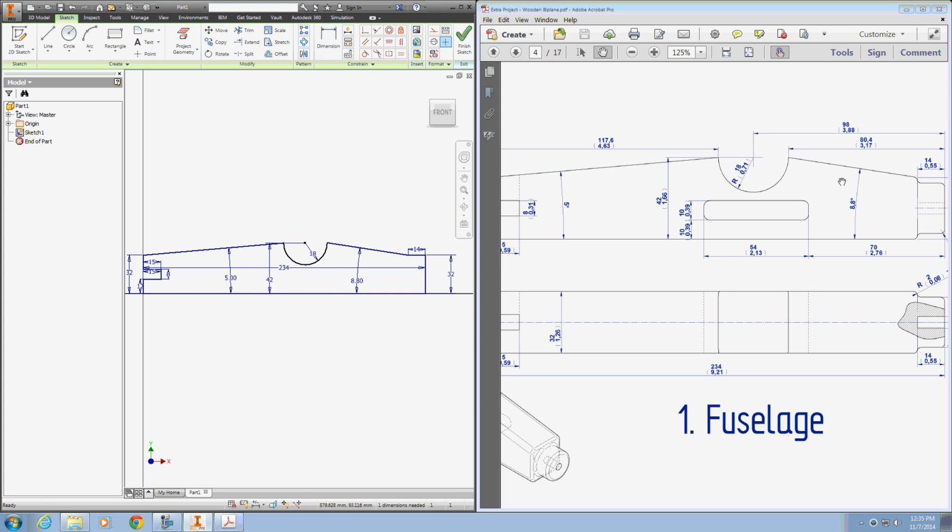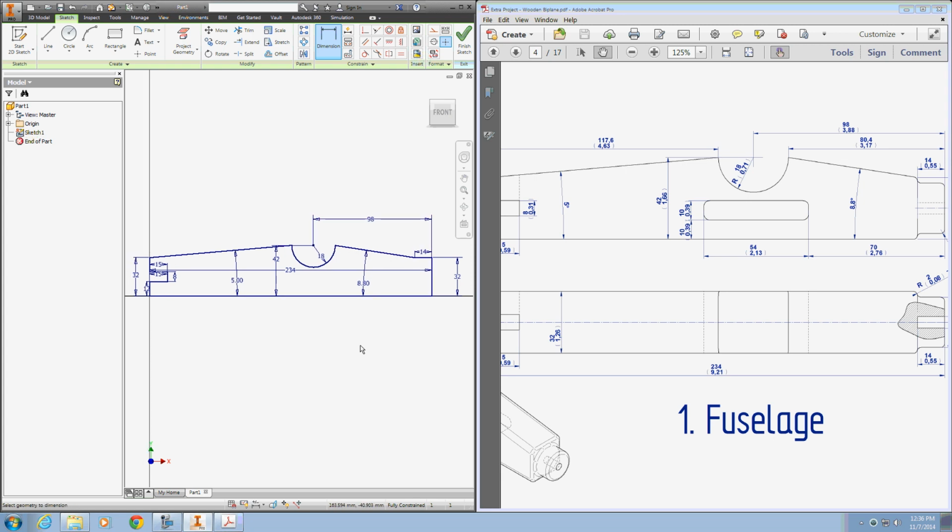And then it is 98 millimeters from the front to the center of the arc. And with those dimensions, it is fully constrained. I do not need to use the 117.6 because the angle and the arc specify where that is, or the 80.4. All of the rest are what's needed.